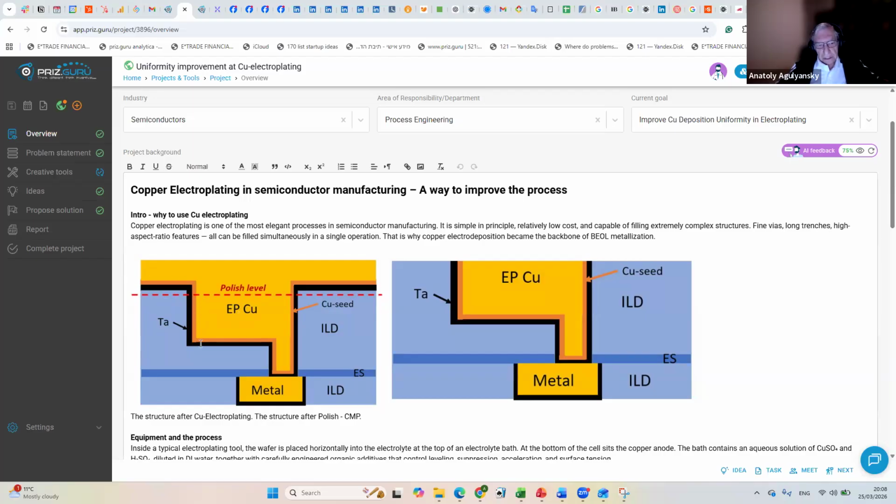And after that, a very thin layer of copper, which is a seed layer. We need the seed layer in order to connect it to electricity and allow electrolysis. So we did it, and we deposit copper. Copper fills in all vias and trenches, and we build a lot of copper above.